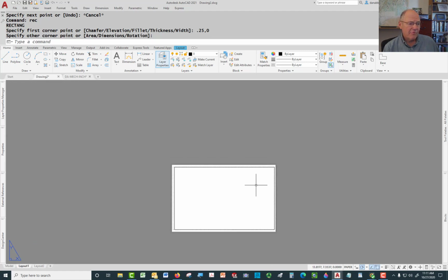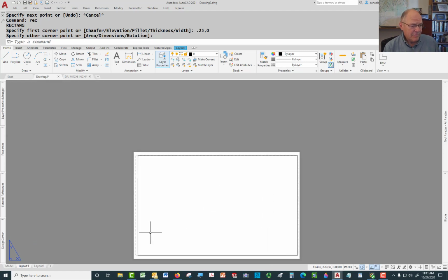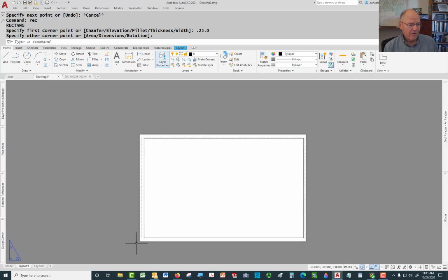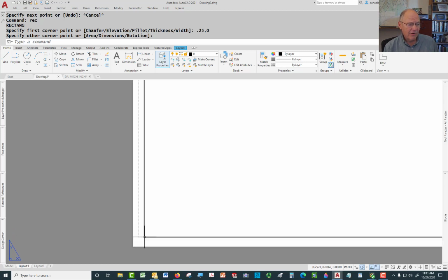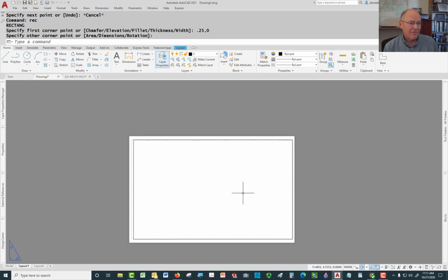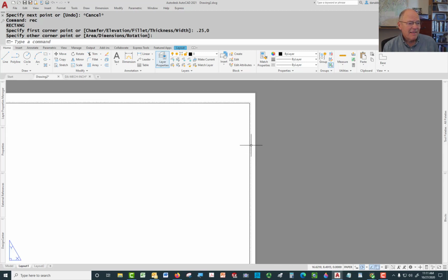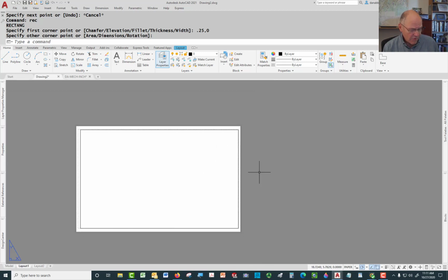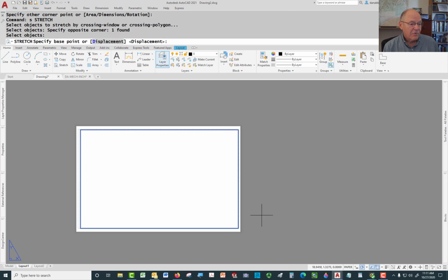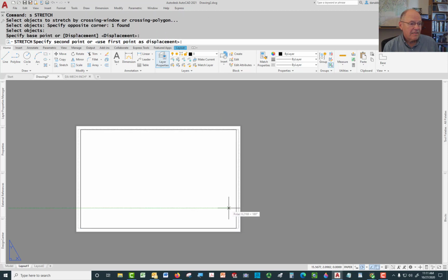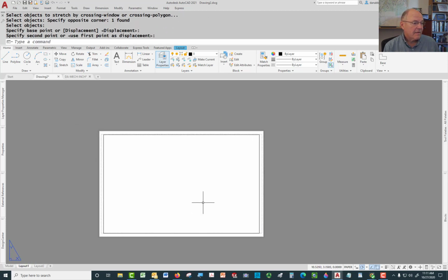Now that means when I start my title block, I want to start the corner of the title block at 0.25, 0, so that when I bring it in, I can just drop it in place as an inserted block without having to identify where it goes. So that's going to give me about a ½ inch here. It looks like about a ½ inch here. And then up here, I think that's a little bit too close visually, so I'm going to bring that in as well. So that's about a ½ inch as well. I think that looks good. So that's what I want.